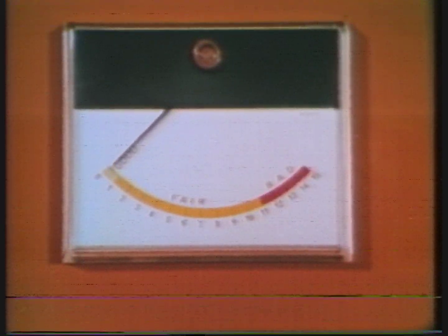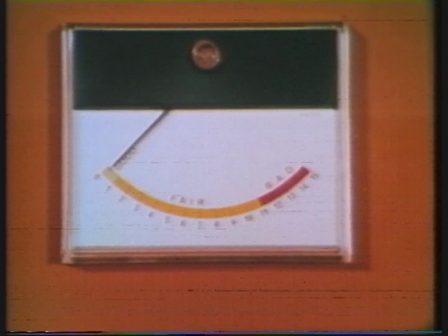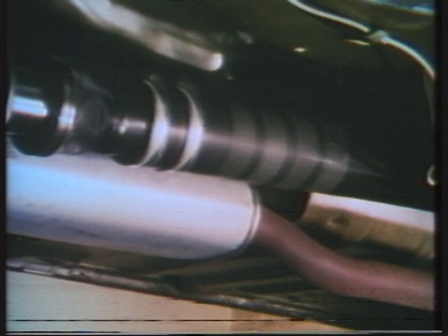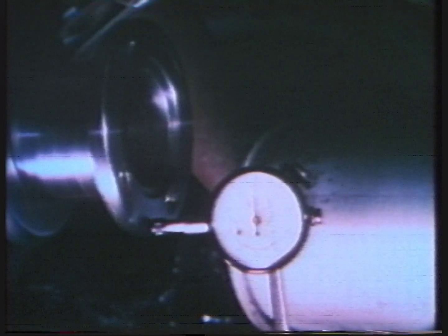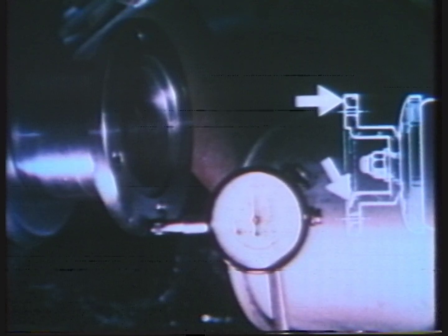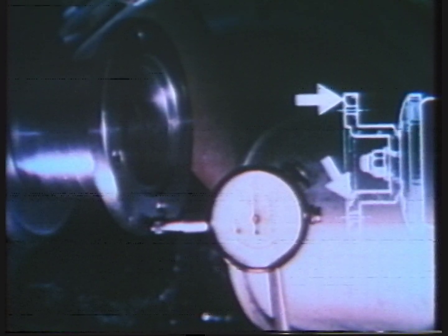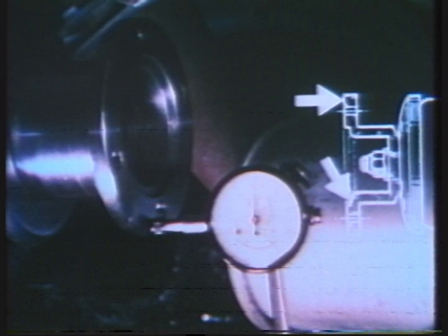Then tighten clips fully. If, when the prop shaft has been balanced, road testing still indicates vibration or boom attributable to the prop shaft, then check the rear coupling, flange face and spigot. Change the coupling if either face or spigot is not within limits. Then repeat the balancing operations.